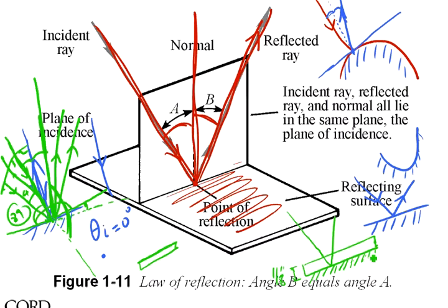As opposed to these here, these mirrors have a little bit of silver, and believe it or not, there is copper in the back of the consumer mirrors that we use at home. That's why if you have a mirror close to an area where it gets wet, the water that splashes will start corroding the copper from the edge, and you start seeing the edge of the mirror getting dark, black. Okay?